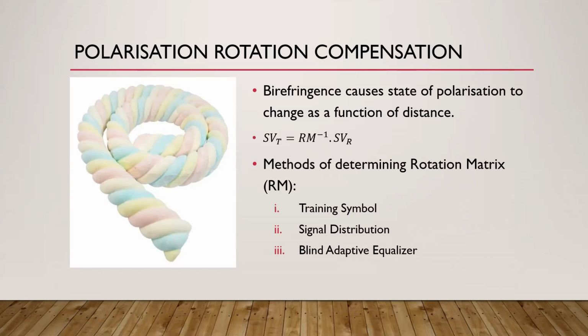But because of the birefringence effect, which causes the state of polarization to change as the signal moves through a waveguide, what we receive on the far end is not going to be that perfect XY polarization and division between the carrier and the modulated signal. We're going to get some sort of a hybrid.